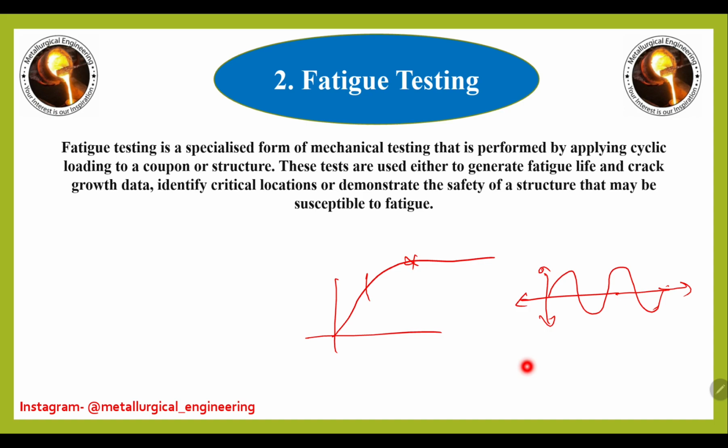What happens during this periodic loading is that the material is supposed to take this maximum load under the tensile test, but under the fatigue test it will take very much less load compared to this. So it is very important to do fatigue testing to understand the material's behavior under repeated loading.